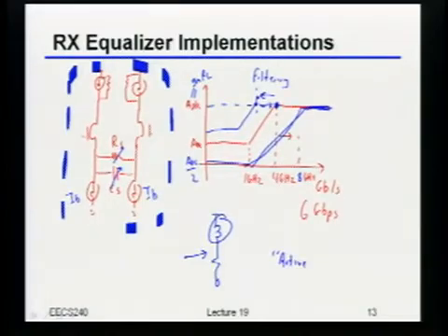So as we'll see in 1 second, I actually claim you've already seen an active inductor. Because if you remember the very first equalizer I showed you, what we basically did was took a transistor, tied it up in a diode connection, but basically stuffed a low-pass filter in the feedback of that diode connection, right?